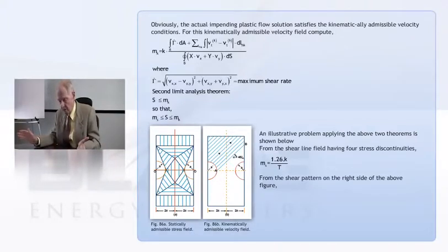That's pretty simple. When you work out what's going on, the only thing you have there is looking at the equations above those pictures at the top. If you look at what it would take to calculate that, for the upstairs part of that M sub k, you have just simply the velocity discontinuity coming in. And the capital gamma dot is 0 everywhere, because you don't really have any strains anywhere except very locally at the shear plane. It's where the sliding's going on.